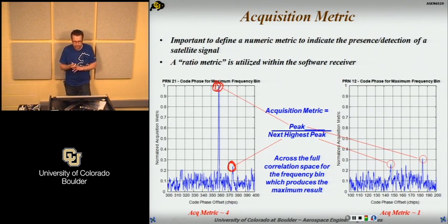And the reason we do this is a little bit complicated. If you record data, and you know for a fact that this is only a GPS signal and Gaussian noise, then you can really just look at whatever the variance of the noise is and use that as your noise floor, go through acquisition, and get a peak. You can predict that if I have a signal with a positive SNR of 20, then this is what I expect. You can figure out how strong the signal is just from acquisition.